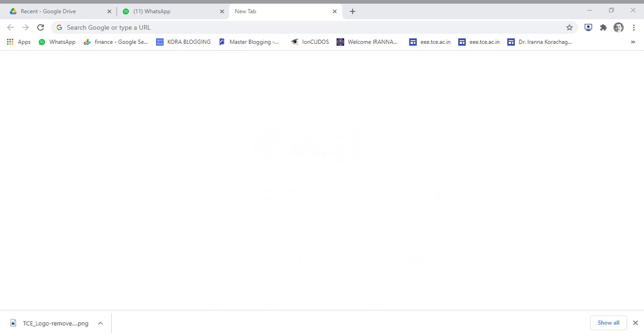When there is no current flowing in the circuit breaker, there is no question of heat being generated. The purpose of this test is that when this is put into operation, currents flow through the circuit breaker. When currents flow through the circuit breaker, heat is generated. And because of this heat, when it starts dissipating to the other parts, we are supposed to know what is the maximum temperature of each part of the circuit breaker.